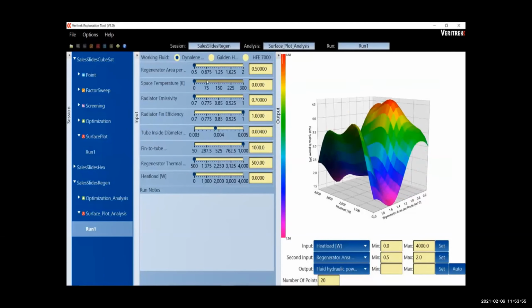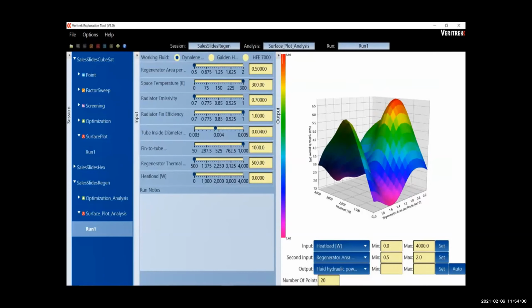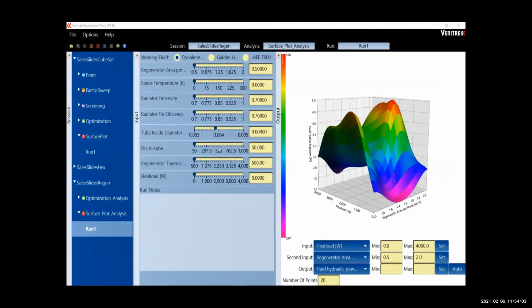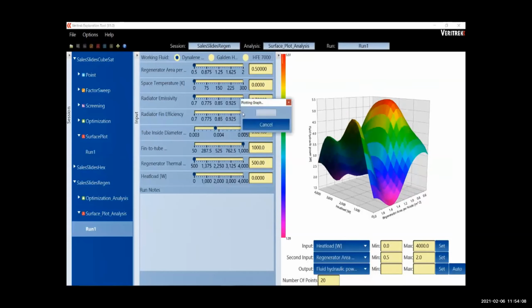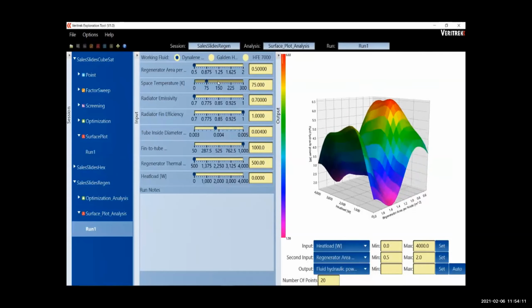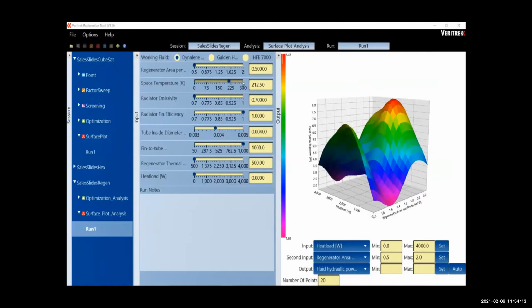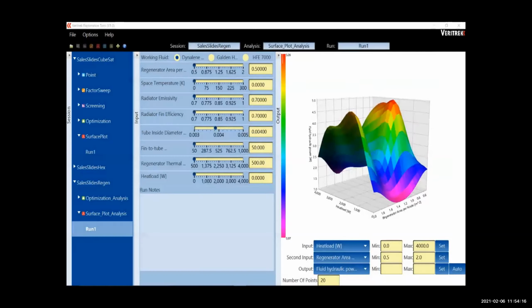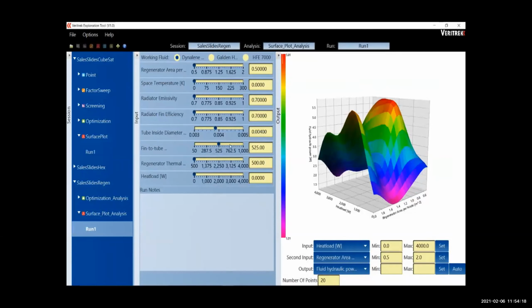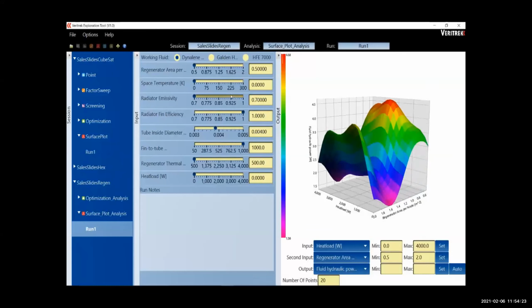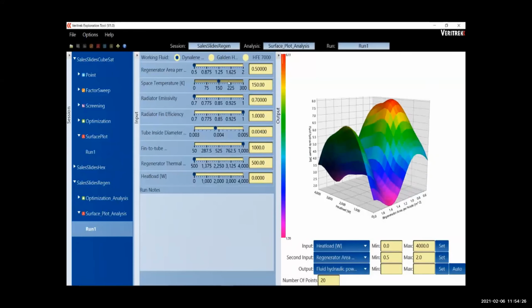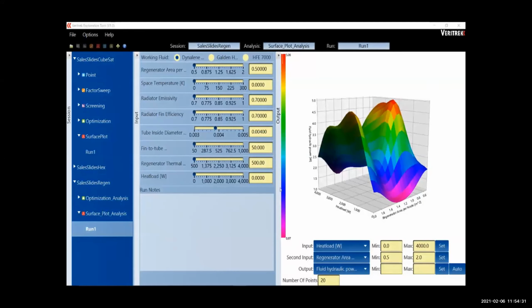And what's going on on the right-hand side is the response to those changes in input factors is changing this response surface. And I think the take home here is that every time we're moving a slider, we're basically running 400 simulations to generate this response surface, to look at the relationship between inputs and outputs. If you wanted to do that in a traditional spacecraft thermal analysis sense, it'd just be too cost prohibitive. You have 400 simulations. It takes minutes, maybe hours. I think that particular model probably took about 30 to 45 minutes to run a single simulation. It could take you a week to generate a single response surface. But by first converting it to a reduced order form, we can generate those response surfaces in near real time.